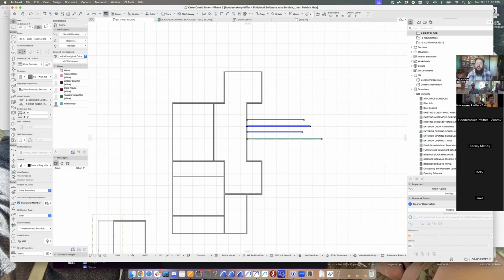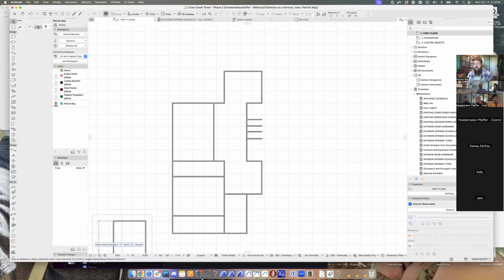It is going to adjust to whichever end is closest. So if I wanted them to adjust to this point here to the left, that's where I would have to use the split command, right? Because if I hit adjust here, it's going to adjust them to the left. If I wanted to adjust the right hand in, that's where I would have to split them based on that vector and delete the remainder.